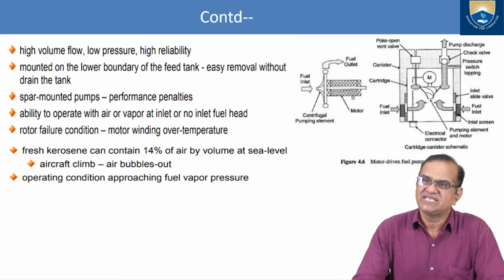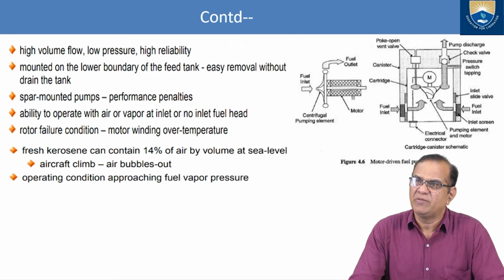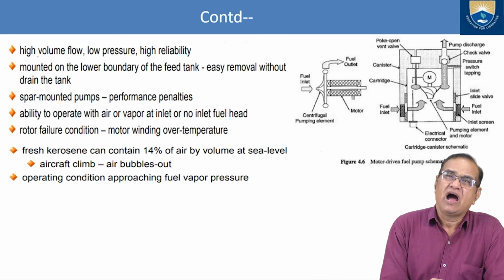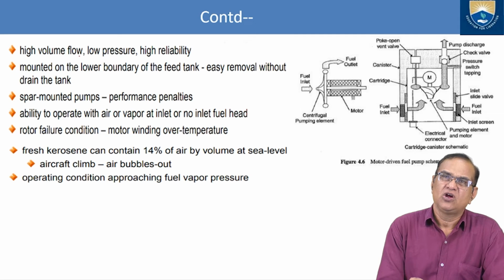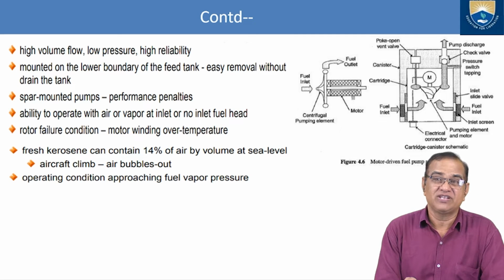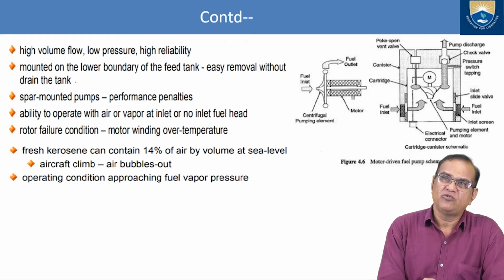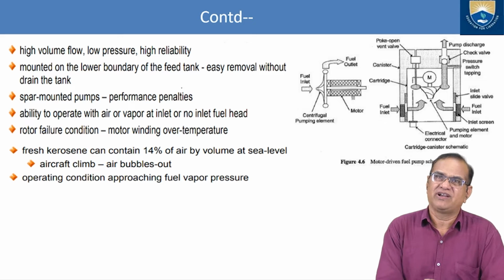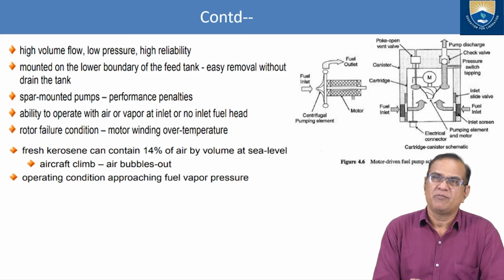Here we can see the motor driven fuel pump schematic, which I am going to discuss. High volume flow, low pressure and high reliability of the pumps are required. The pump is mounted on the lower boundary of the feed tank for easy removal without draining the tank. For spar mounted pumps, there are performance penalties.